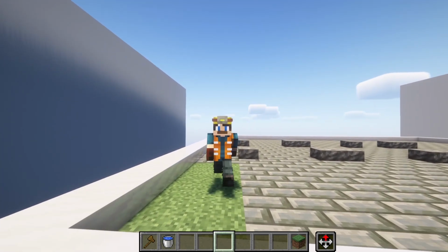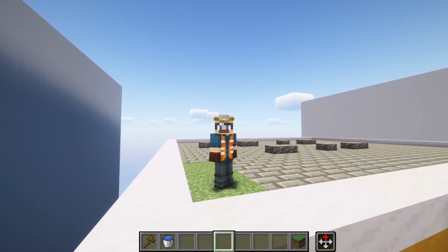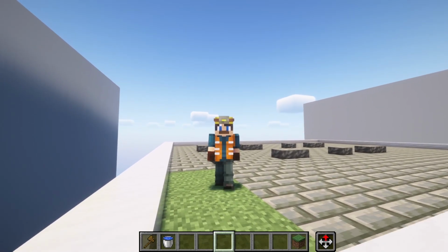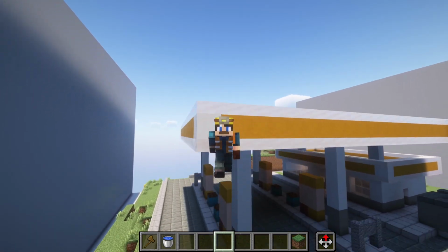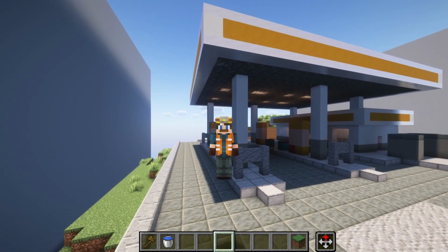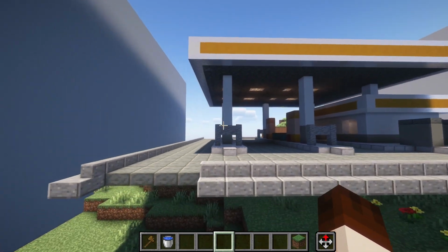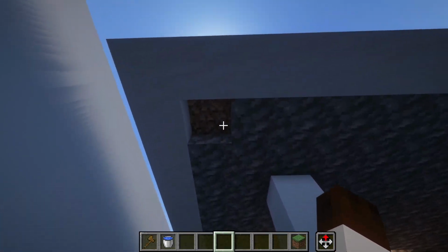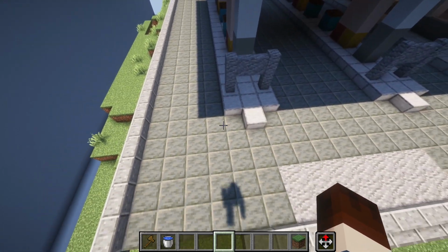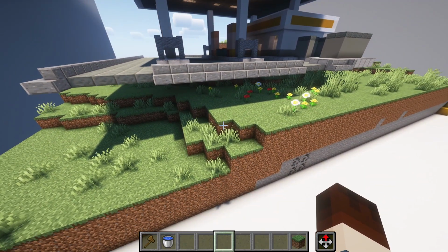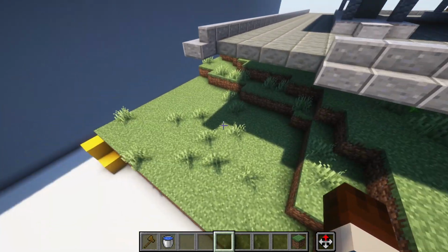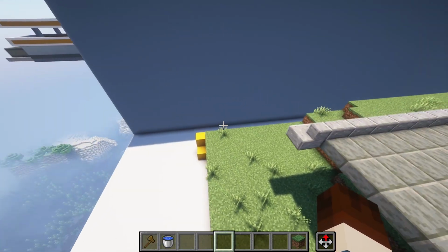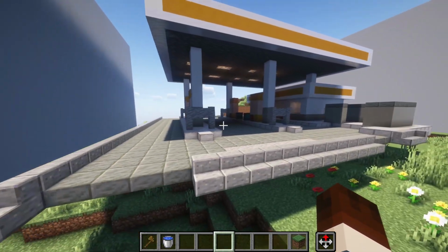This allows for the plants and other things to clean the water, improving the water quality, but also allow it to permeate through down below and then probably through some sort of underground infrastructure or pipe network where it eventually falls through a gutter and down into the remaining stormwater management infrastructure, which is some sort of storm sewer along a road network or a nearby retention or detention pond.